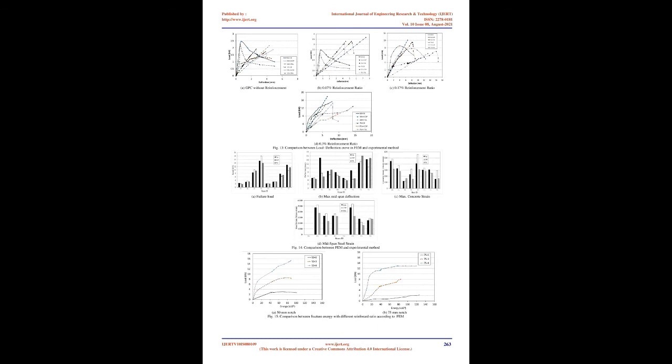identical in tension and compression. It is used for the longitudinal steel reinforcement in the beam and it is defined as linear isotropic for the elastic zone of the steel and bilinear isotropic to define the second part of the curve as a straight line. Bilinear isotropic material is also based on the von Mises failure criteria. The bilinear model requires the yield stress, also the modulus of elasticity, E, and the Poisson's ratio.